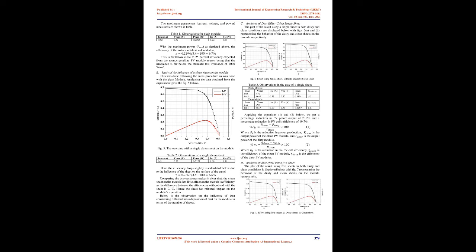D. Experimental setup. The experiment was set up indoors in the postgraduate laboratory of the Faculty of Engineering and Technology in the University of Buea as shown in Figure 3. The cells were connected in parallel to put the module to full capacity. To eliminate the effect of ambient light, as it is not very stable and has an impact on the module, a black box was made to contain the panel and the light source, while the multimeters and 0 to 100 ohms variable resistors were placed out of the box.